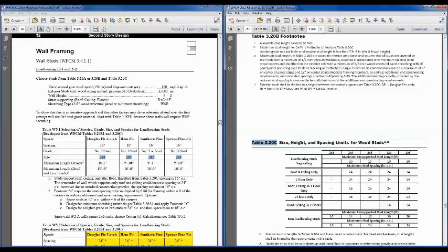So there's two checks that we look at. We look at in the workbook a maximum wind load check, and then we look at a maximum length based on dead and live loads, and those dead and live load limits are based on this table here in the table 320C in the workbook, and those come right out of the IRC.